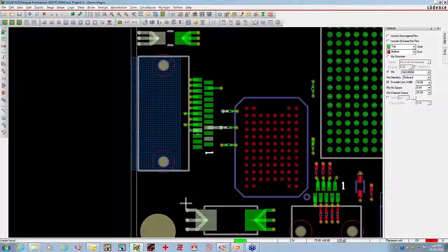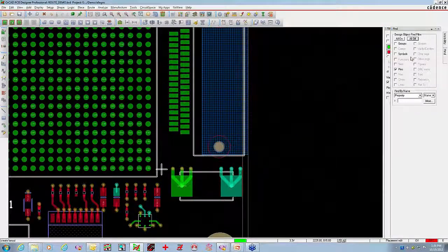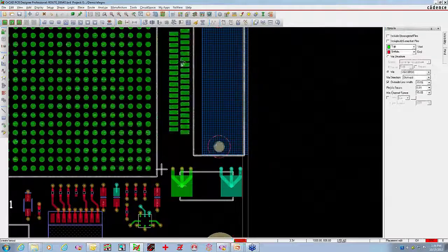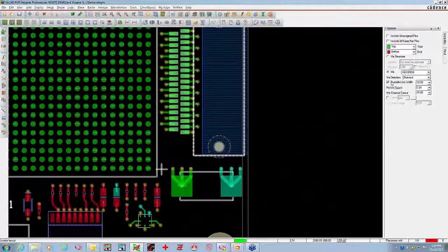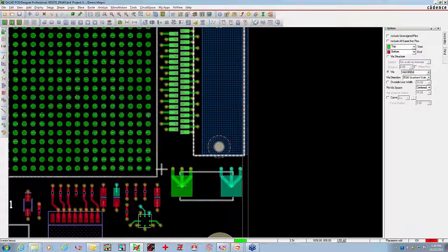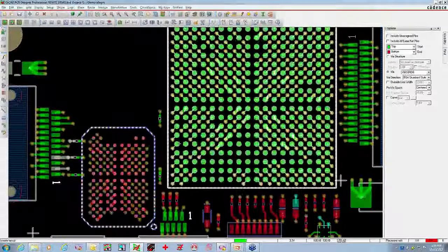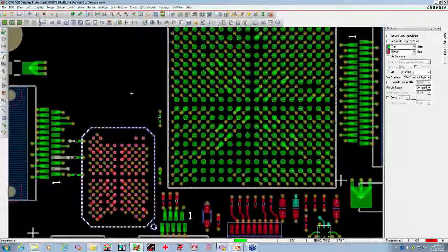So again, I'm just going to repeat what I did. I'm going to swipe a window around these so you can do it that way. In my find filter, I'm going to go up here and select this as a symbol, and I'm doing those outward. I'm going to take off my override line width. I'm going to do my BGA quadrant style now, and I'm going to center those in between the pins. So I'm just doing my active pins. I'm going to select my BGA that's on the bottom of the board, so you can see it did the quadrant fan out the same way as well.